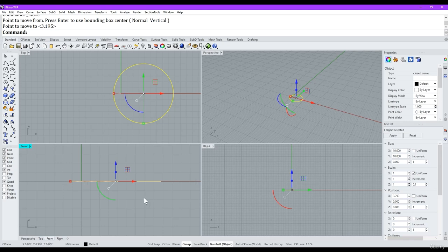We've just moved across in the axes. So if project is not enabled, you can get into trouble. So just keep it enabled until you feel like you want to disable it. Generally speaking, I've got it on 99% of the time. There's just that 1% where I just need to move somewhere in 3D space. So I'll disable that, but then I'll make sure I re-enable that.